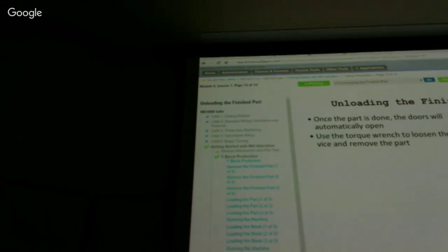An end mill goes out like that. There's some cutting flutes that go up it, right? As it spins, and if you looked at the bottom, you'd see some cutting flutes there. So as it spins, those cutting edges move through the workpiece material, pull the chips away, removes material. Right? So if I'm using this, and I want to make a shape that looks like that, that's hard to do, right?